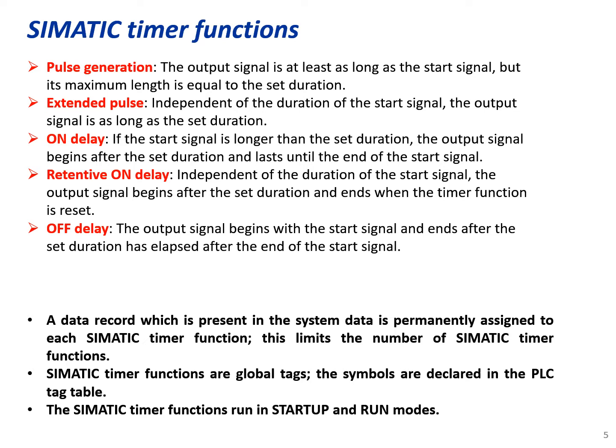Retentive on delay: independent of the duration of the start signal, the output signal begins after the set duration and ends when the timer function is reset. Off delay: the output signal begins with the start signal and ends after the set duration has elapsed after the end of the start signal. Again, you might need to go back to this slide and read those descriptions again.